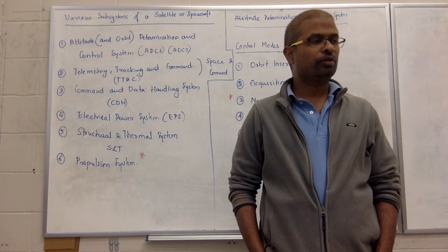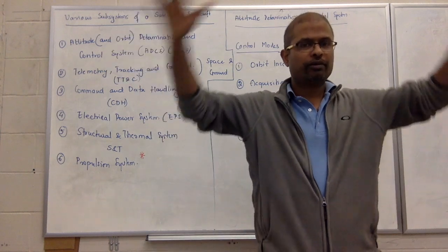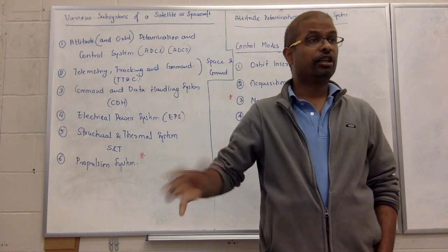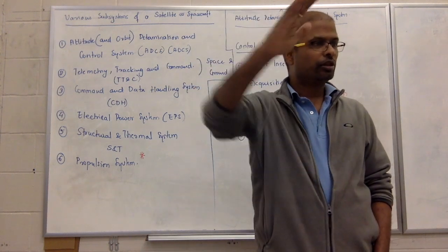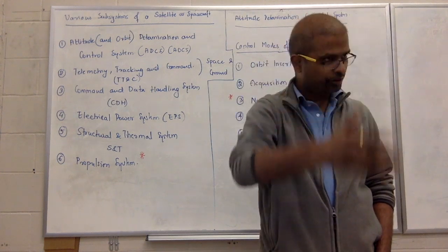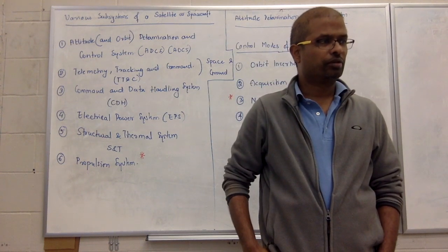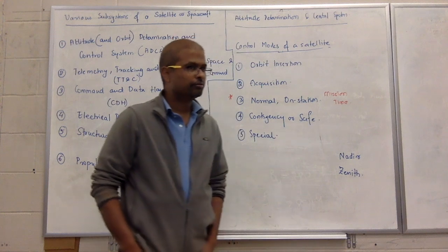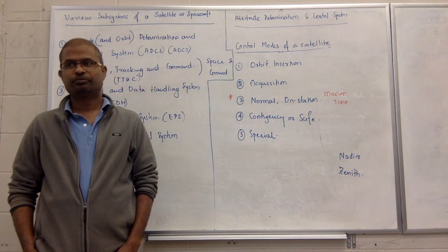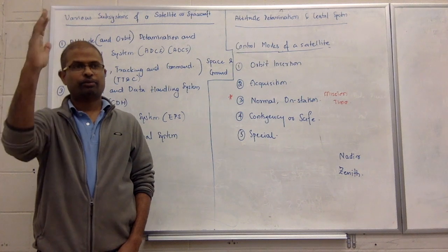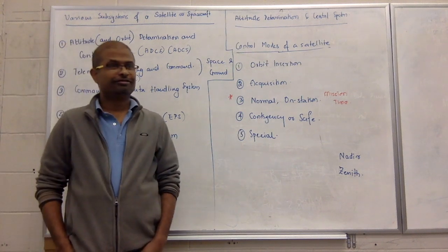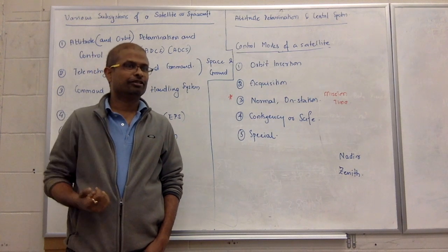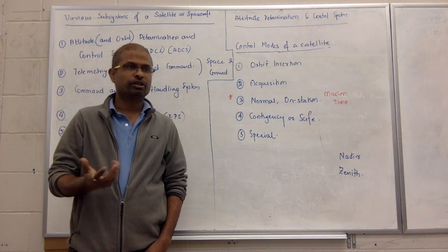You can do the same thing to a satellite. You have a square satellite, let's say, and you attach a big load at the end with a big boom. It will align with Earth's gravitational field. What kind of satellite would that become eventually? It will become a nadir pointing satellite.